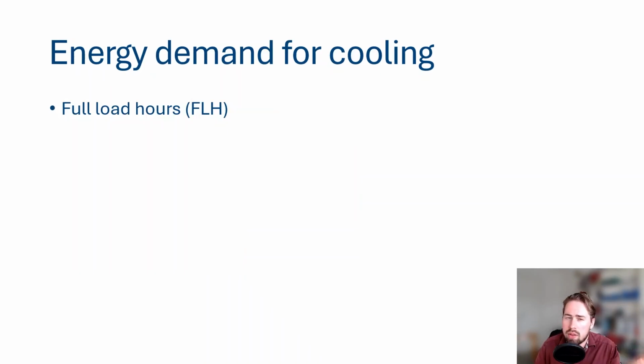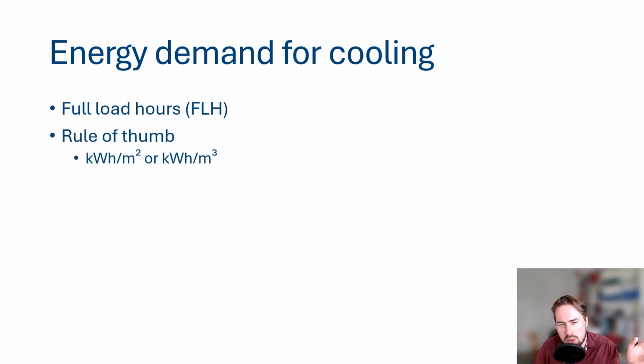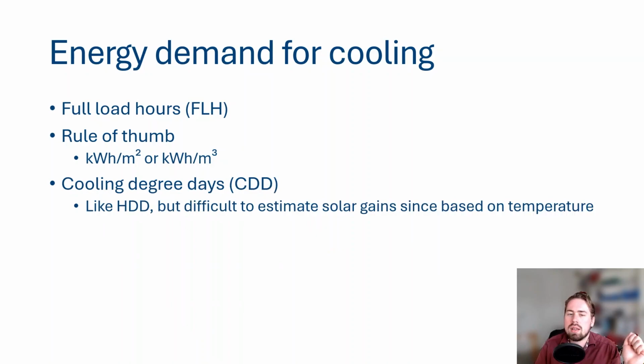For the cooling demand, it's the same story. Again, here you typically work with full load hours. Again, you also have rules of thumb for kilowatt hours or kilowatt hours per cubic meter. You also have cooling degree days, which are the same as the heating degree days, but the other way around. So you again have a threshold, and when the temperature is above the threshold, you sum this area, and the total sum for an entire year is then the cooling degree days.